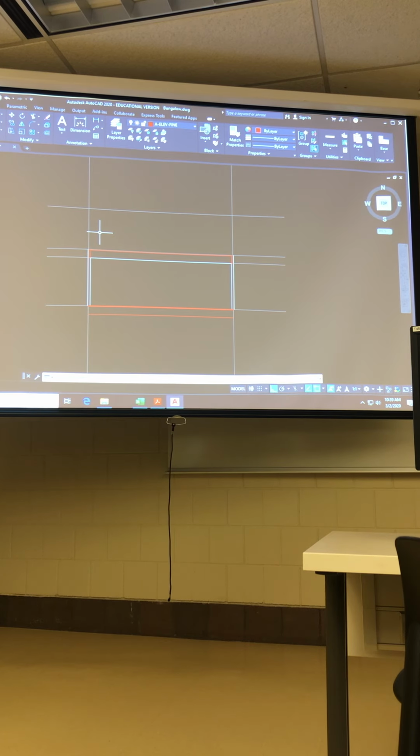All right, so I'm gonna start on the roof structure. And what I'm going to do is go back to my handout, and I'm going to see that, okay, this roof structure again is this big attic storage truss. And I can see that the truss has what's called the truss heel. Over here, there's a dimension of 3 feet 9.5 inches, and that is from my truss bearing datum elevation, this one down here, up to the underside of the roof sheathing at this point.